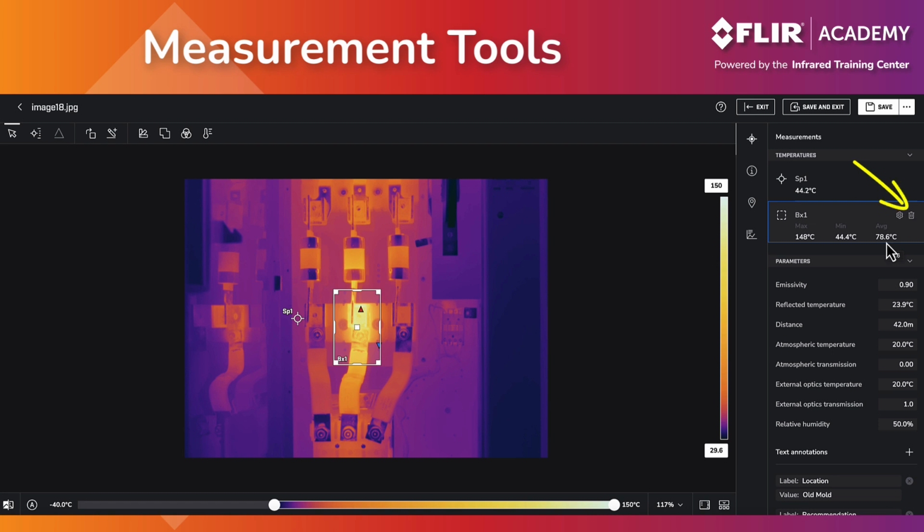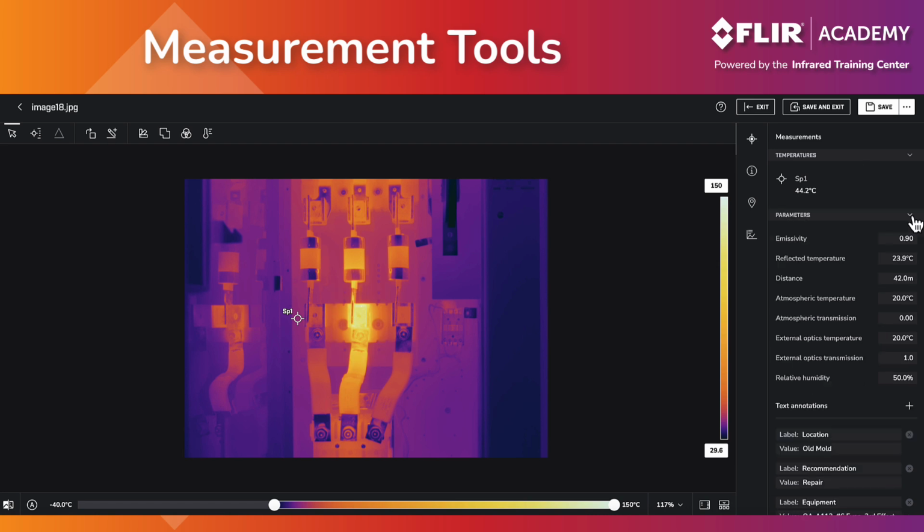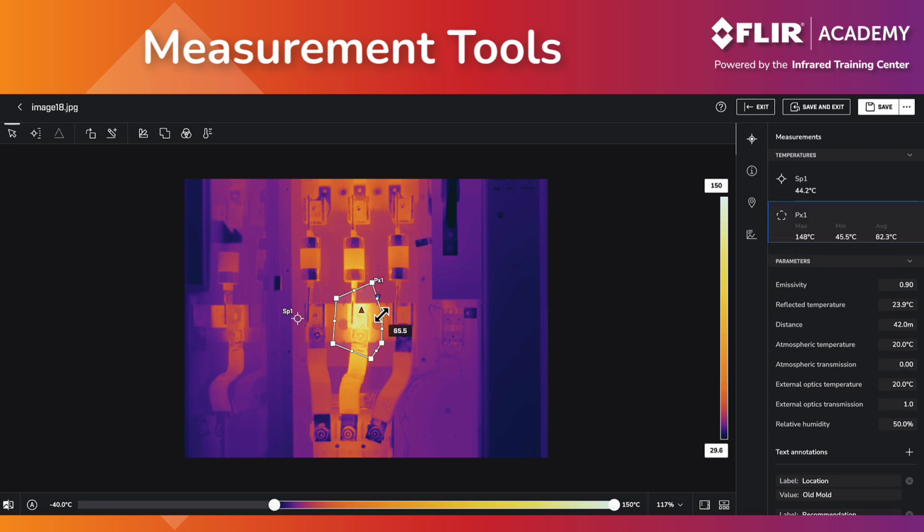To remove a measurement tool, select the trash icon to delete it from the image. Also available is a polygon area tool. To set this, click once to anchor the shape. Subsequent clicks will then add another side to the polygon. Double-click to lock the polygon in place once you have drawn the desired shape.